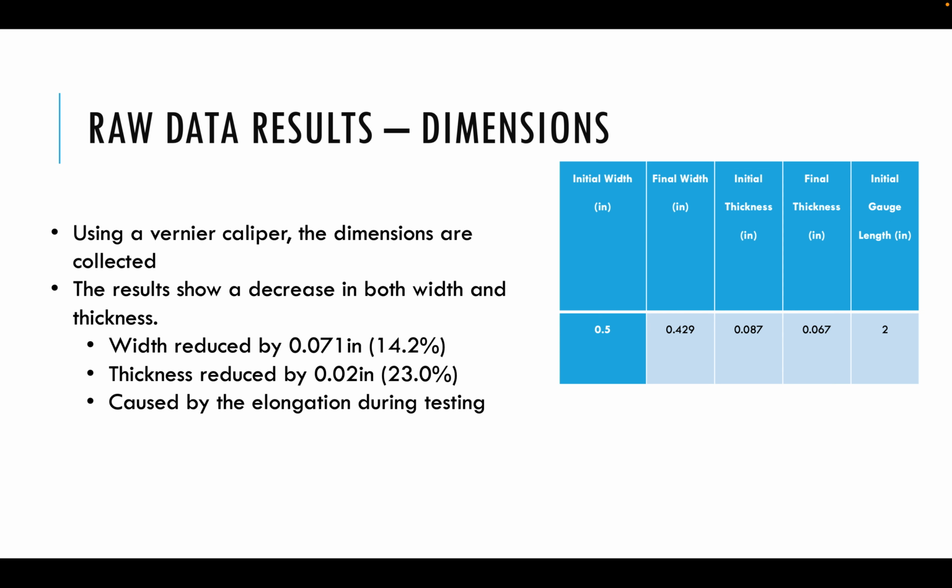This means that the cross-sectional area decreases as we apply the tensile load. Recognizing the changing area is crucial, as we later use this fact to derive the relationship for true stress and strain.